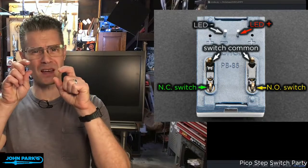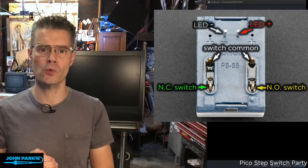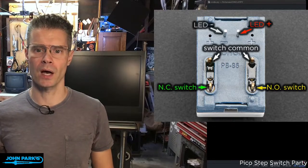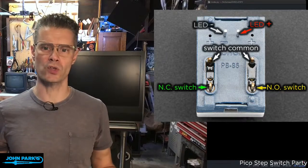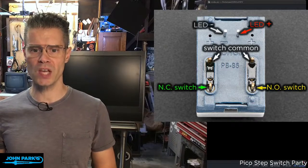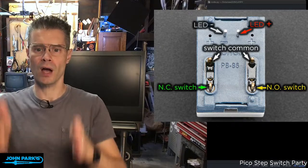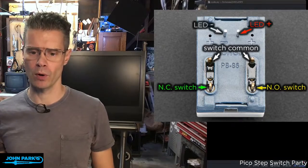Then there's essentially a normally open and a normally closed side of a switch there, and a common running along it. And you can actually pair up all these ones that I've illustrated in white here. You can send all those to ground if you want. The normally closed side and the normally open side of those are in line vertically with their common side, which means you can't put this into a typical breadboard.